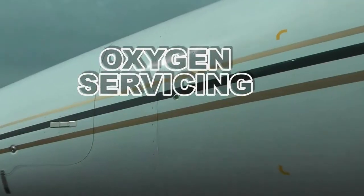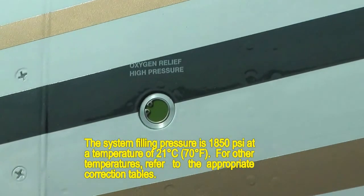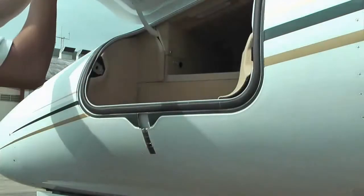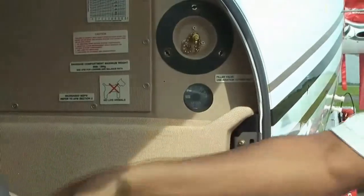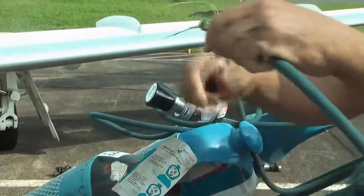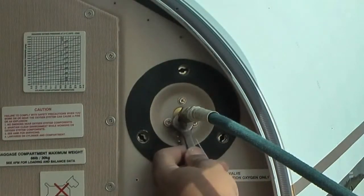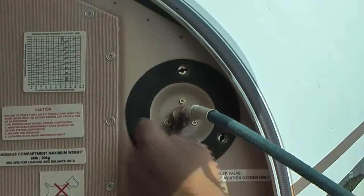Oxygen servicing. Filling operation is carried out as follows. Check the overboard discharge indicator to make sure the oxygen has not been discharged. Open the oxygen compartment door. Remove the protection cap from the fill valve. Connect the pressure oxygen servicing regulator to the oxygen source. Connect the oxygen charge adapter to the oxygen servicing regulator. Connect the oxygen charge adapter to the fill valve and make sure there is no leak.